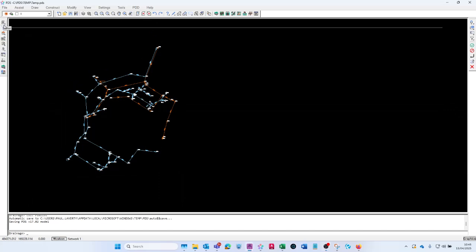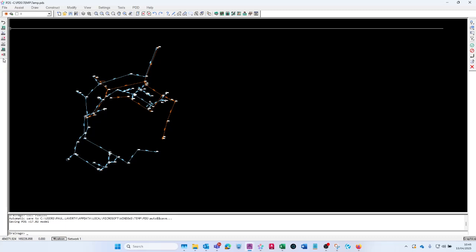So within the drainage module, you go down to the profile sections, it's this little icon. You click on it, you go into the sub toolbar, and here we have the profile with what looks like two arrows in a circle pattern, and it should be the Gen Section button. So you're going to generate the section on this.